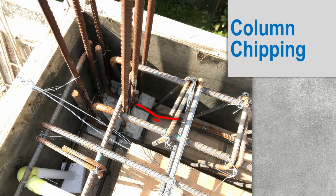It is advisable to chip the column at least to the formwork level, and there are several errors in this area. As I showed previously, here you can see a small nail is used to fix this formwork. If this nail is loosened, this will collapse. Therefore, we have to follow correct and standard construction practices.